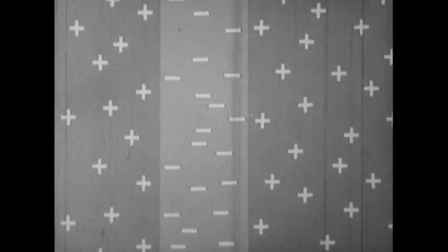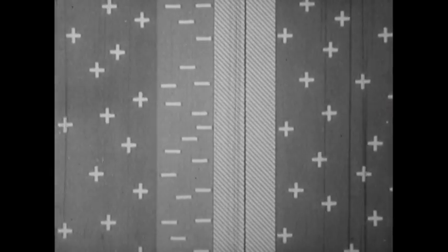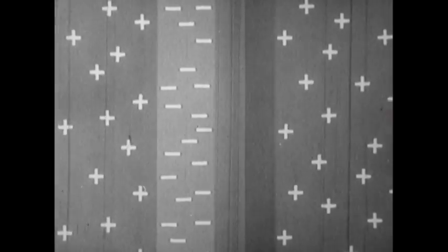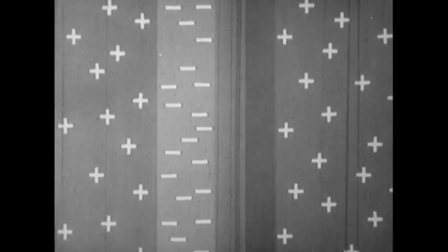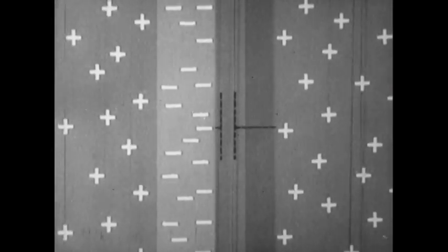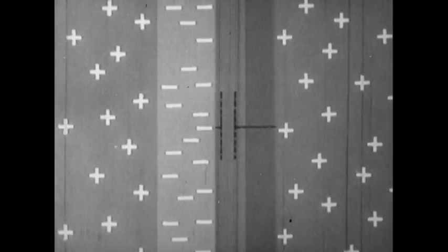This capacitance results from the behavior of the majority carriers, holes in the collector, and electrons in the base. The reversed bias draws all holes and all electrons away from the collector junction. This leaves a vacant region at the junction, a region of insulation that acts as a dielectric between the two adjacent layers of conductive material. It's equivalent to a capacitor connected between the base and the collector.